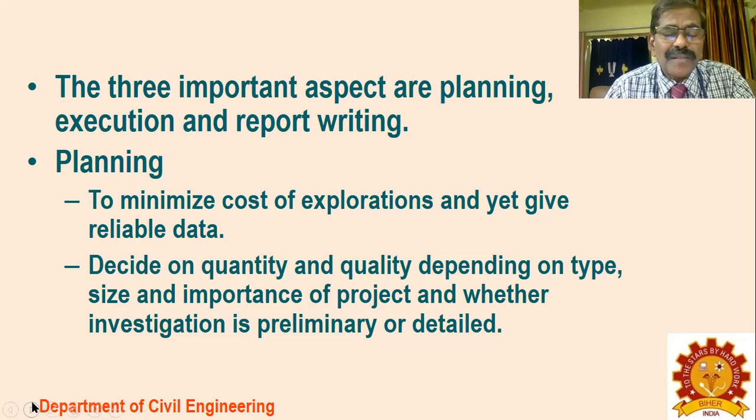type, size, and importance of the project, and whether the investigation is primary or detailed. Some primary, reconnaissance investigations are possible at the site, but some detailed investigations are also very much required, because the detailed investigation only will tell you the bearing capacity, water table locations, location of the weathered rock, location of the hard strata, location of the clay layers, and drainage capacity of the clay layer.